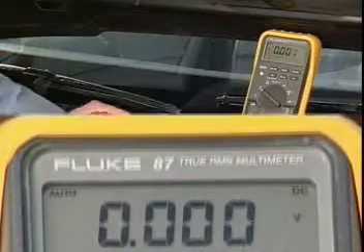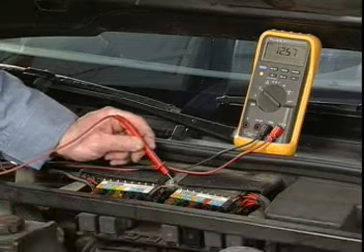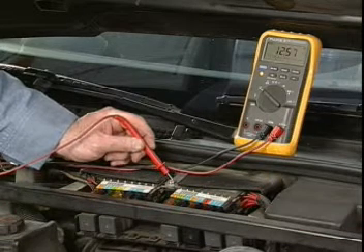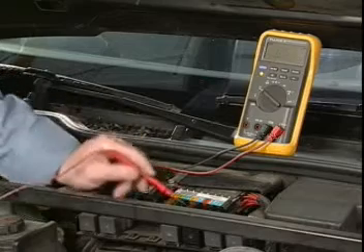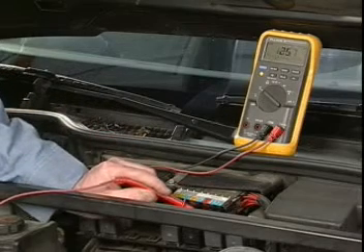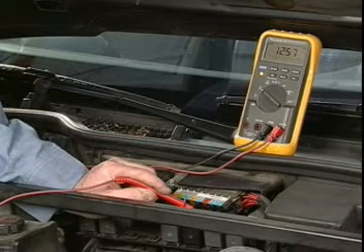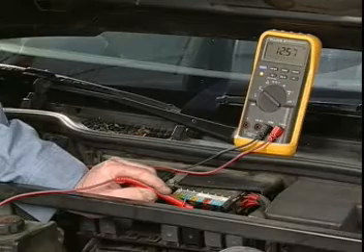The connectors at the fuses, junction blocks, and switch terminals make convenient points to check for voltage. Move the voltmeter lead from terminal to terminal down the circuit until the specific wire causing the problem is identified.